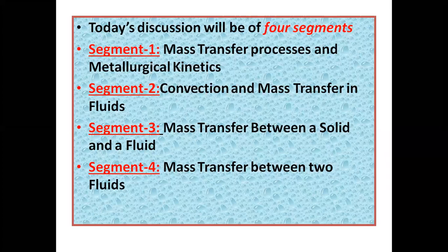If carbon dioxide is formed and the temperature is quite high, what will happen? Whenever you look at the carbon-oxygen diagram, it is seen that at high temperature carbon monoxide is stable. That carbon dioxide will immediately combine with another carbon present in the system to form carbon monoxide. In that case, the positions of the carbon monoxide and oxygen are not fixed inside the bath. They are moving here and there in random motions, so mass transfer is taking place. Why are we stirring? For mass transfer at a considerable rate.